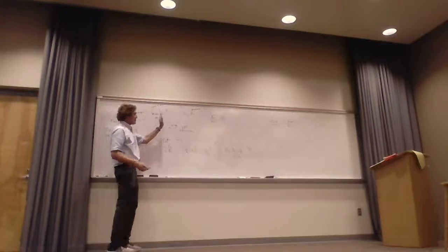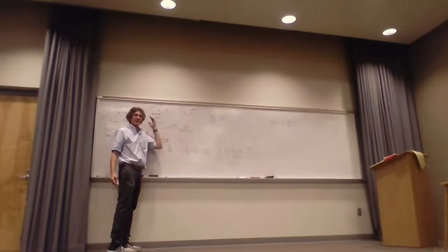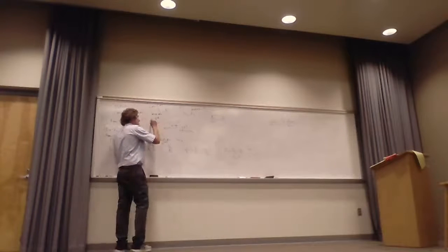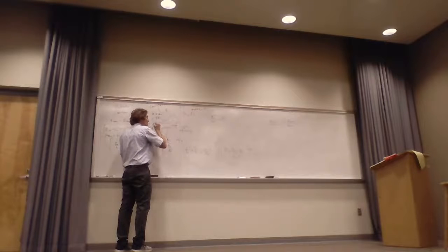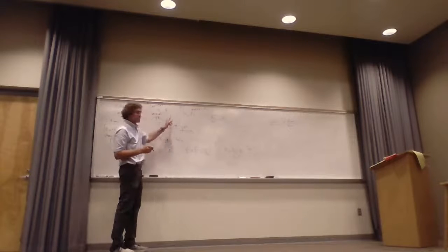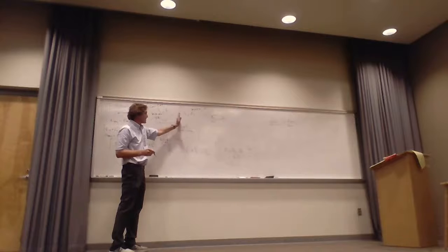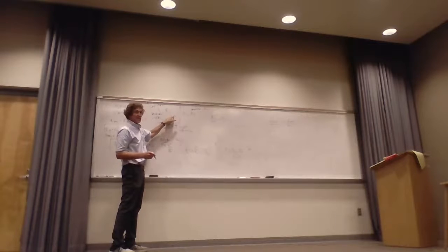I've got electric field coming in here. It hits, and some of it is reflected. The superposition of the incident and reflected waves causes a pattern like this, where there is a maximum and a minimum. For instance, if this is a perfect conductor, then the electric field would short out to 0 there. Therefore the reflected field would have the same magnitude as the incident field but opposite sign, so you would get 0 E field here, and twice the E field exactly a quarter wavelength away, if you remember that stuff.